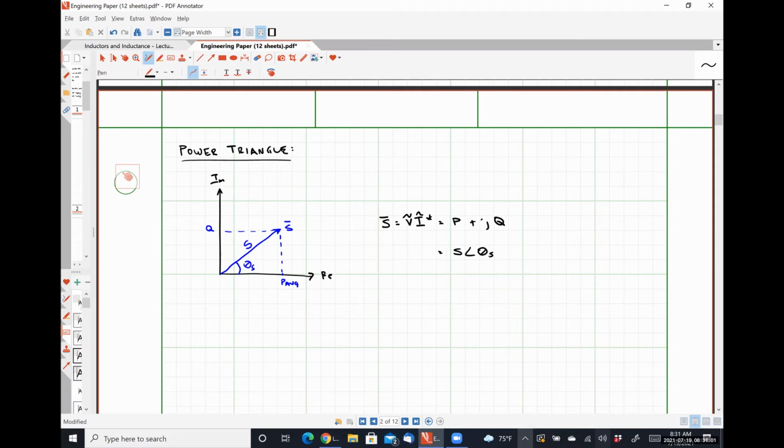If our power triangle wound up in quadrant 4, that would mean our load is capacitive, because our phase angle is negative. We would know that it's absorbing because the real portion is positive while the imaginary portion is negative. There's a ton of information that can be gleaned just by a quick glance at these power triangles.